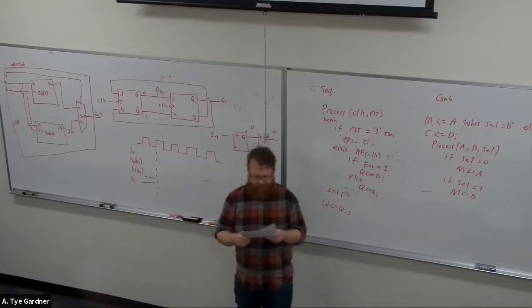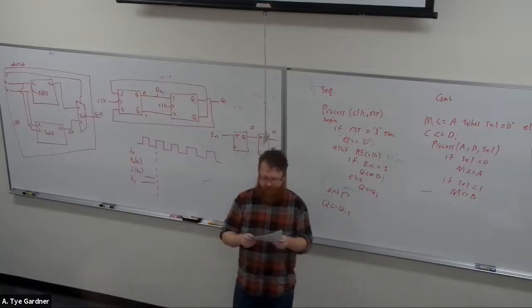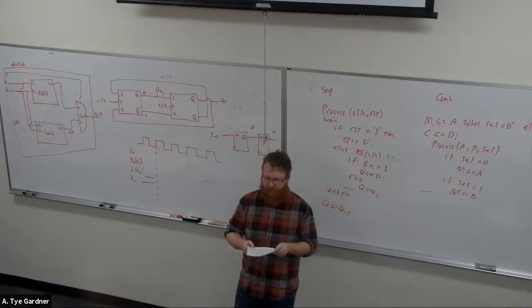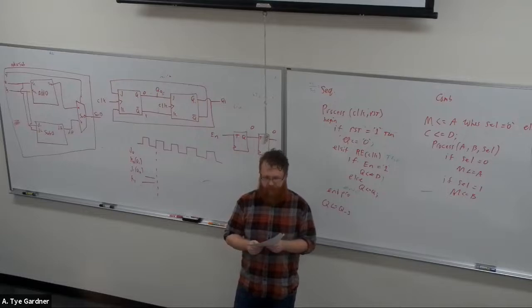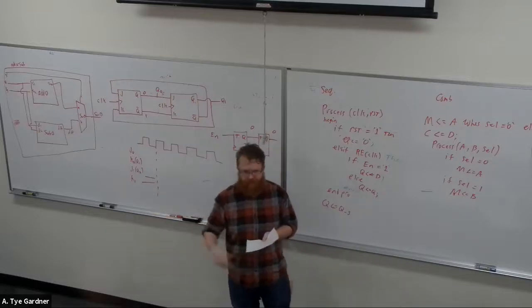True or false, the order of concurrent VHDL statements may be changed without affecting the way that the model functions. True or false? What was the question? The order of concurrent VHDL statements may be changed without affecting the way the model functions. True. True, right? Concurrent, combinational, same thing.